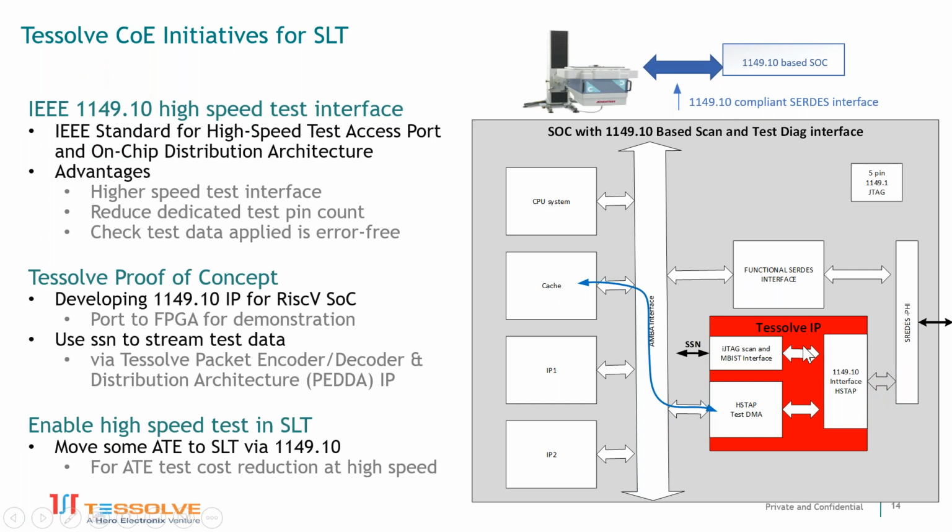Yeah, go ahead. Question? Yeah, I have a question. When you're describing moving tests from ATE to SLT, I'm assuming you mean the die would then be packaged in between and then tested in an SLT environment. Yes. So in your experience, if you package the part and then find out it's broken, I would assume that increases the scrap cost. But are you saying you would still have a financial benefit even with higher scrap costs, because now you're burning a package as well if you find a fault?